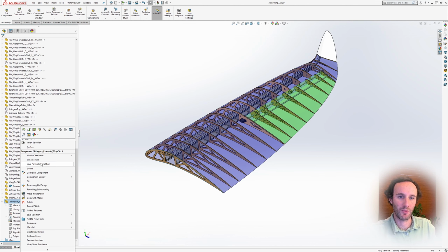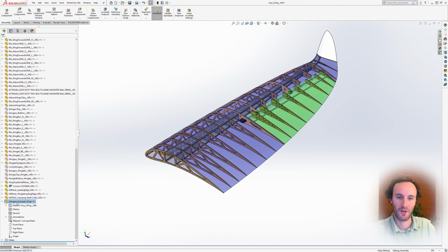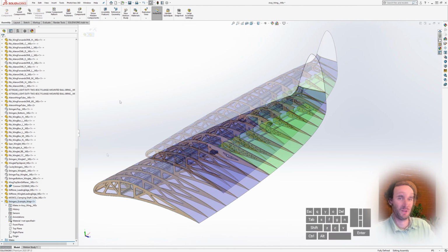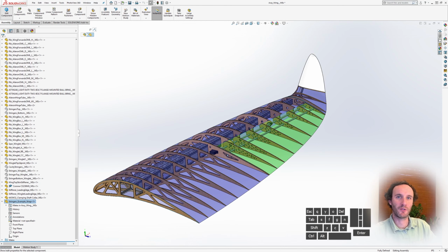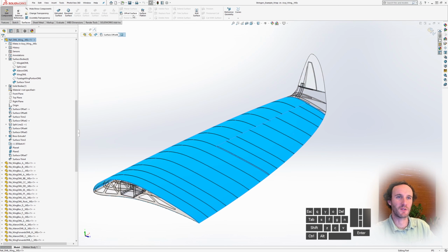And then we can save it in an external file in here. And this we're going to edit in context. So let's do a walkthrough of the swept boss first. So first we're going to, in context, go and grab the surface references. So we can either grab them straight from clicking them there, or we can grab them from the bodies list within the part, the reference surfacing.